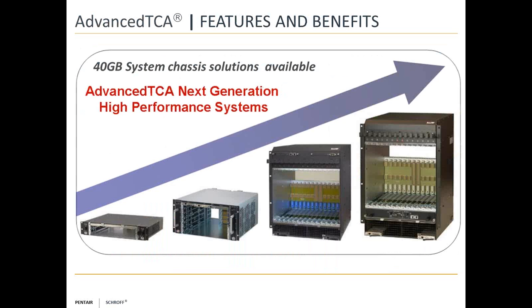Okay, there has been an increasing demand for power and cooling for ATCA boards, and the next generation of ATCA boards will continue this trend. Luckily, the latest ATCA chassis are ready and available from leading manufacturers to meet this market demand, and these latest ATCA chassis support greater than 400 watts per slot cooling, and they have 40 gigabit per second bandwidth backplanes.